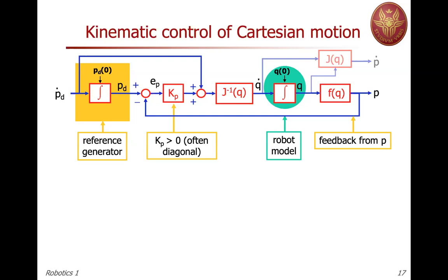Pay attention, even if you're not crossing the singularity, we have seen this effect, we're getting close to a singularity. When Q dot increases suddenly, we have two things. It's not only that we are violating the limit of Q dot, so of the actuators, but we may violate the assumption that the internal low-level controller is an ideal one, because large variation of Q dot means large acceleration, and then we may not be able to reproduce this sudden variation of commands into the actual velocity.